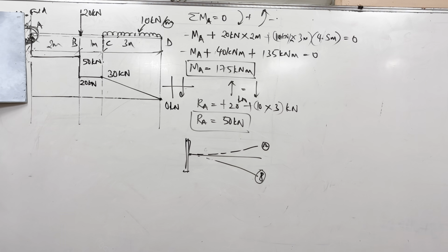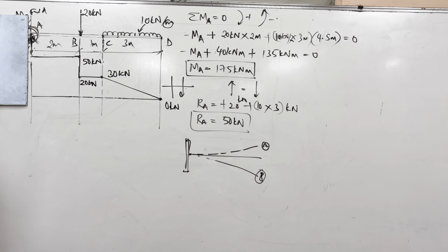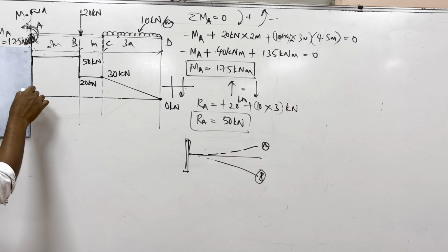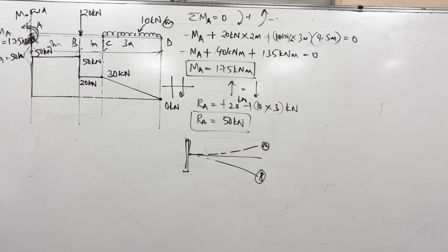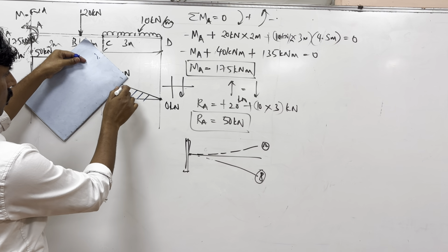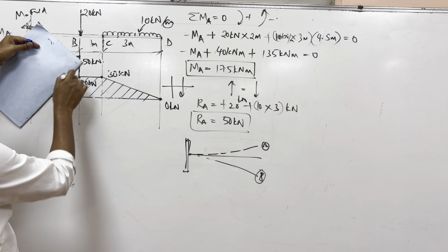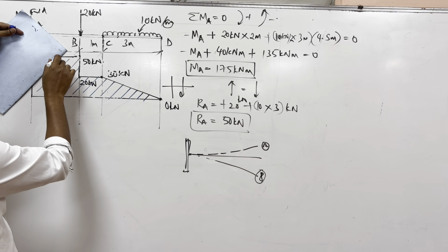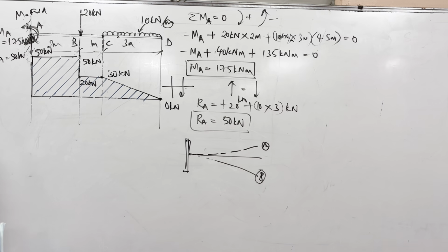When you see this reaction force, one force going upwards on the right hand side is negative. So from plus 50 it goes to 0. Once you have drawn this, you understand that there is a huge amount of shear force at the fixed end. Okay, and then to draw the bending moment diagram.